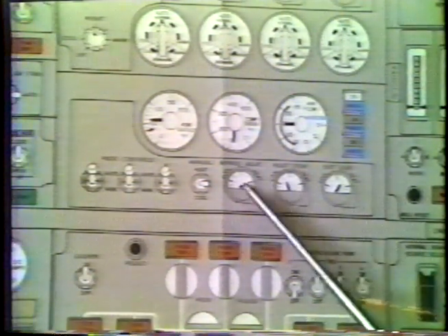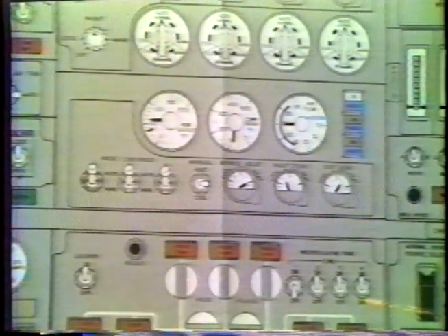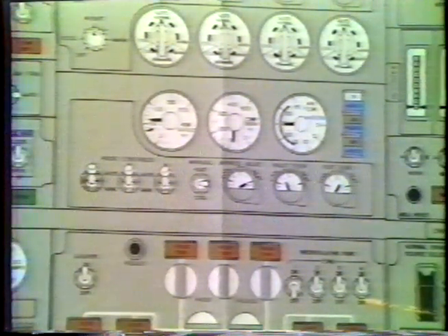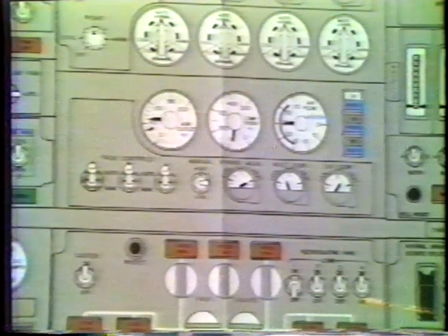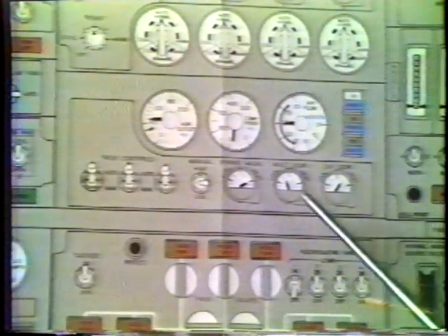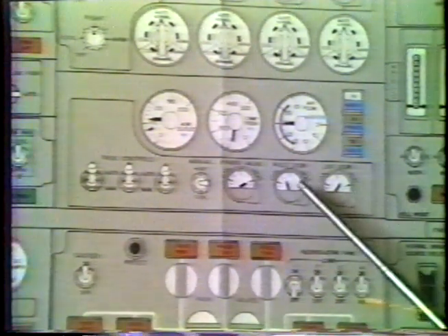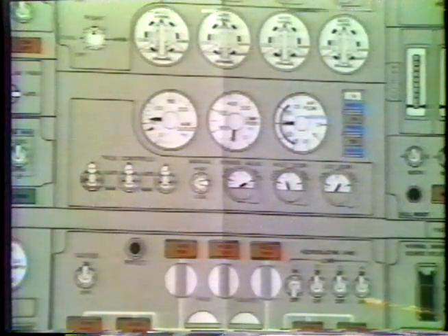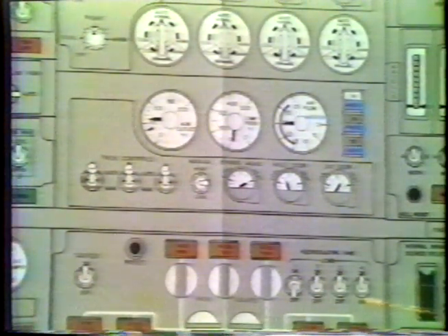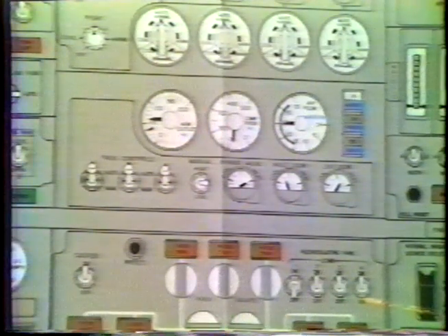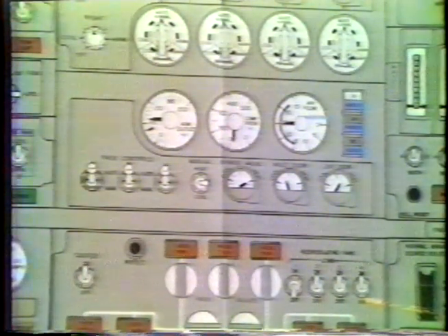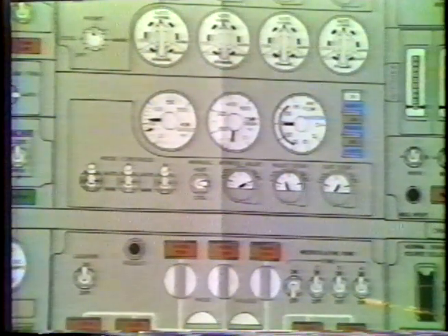And the third thing that will cause a pack trip is the bypass valve out of sequence with the inlet door. By out of sequence, I mean normally you are operating the bypass valve to control the temperature or the inlet door to control the temperature. If both of them are operating at the same time, that is incorrect, and that would cause the out of sequence to trip off the pack.